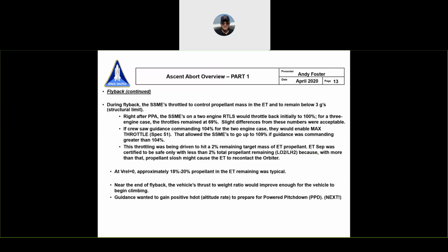And so the rest of it I kind of already talked about. The reason that you want to start climbing is what the next maneuver you're going to do: you're going to pitch down and you're going to bring the engines back to idle when you do it. But the instant you pitch down for separation, and I'll talk to you about why in a minute, you've got the nose pointed down, the thrust is pointed down, it's going to start killing off your altitude rate and pushing you down into the atmosphere. So obviously we'd like to get as high as we can get.